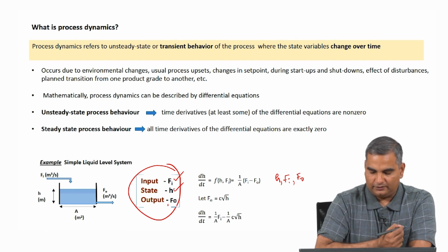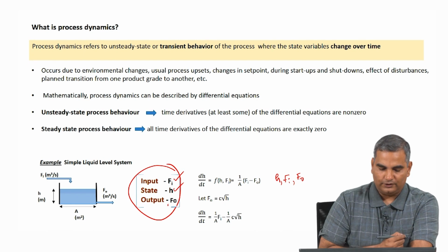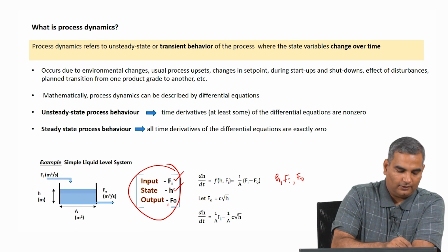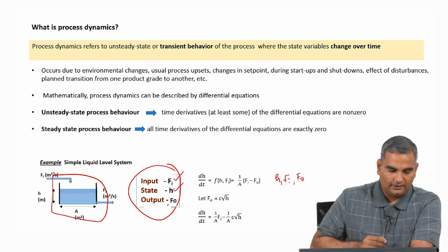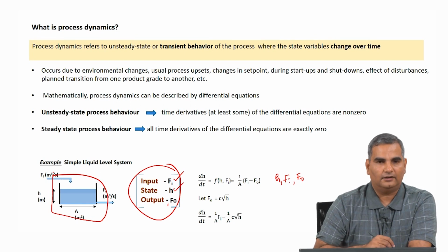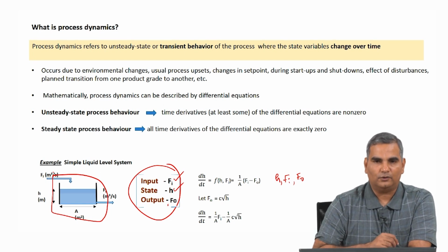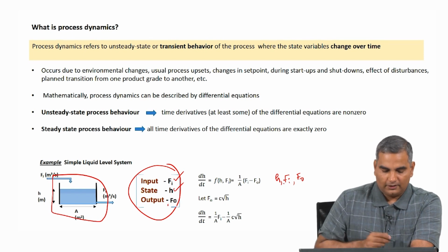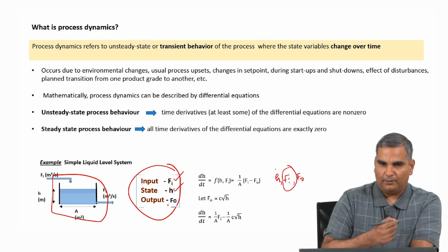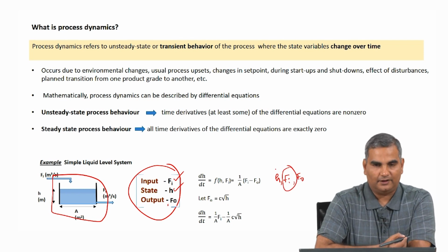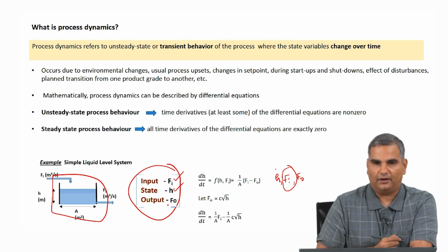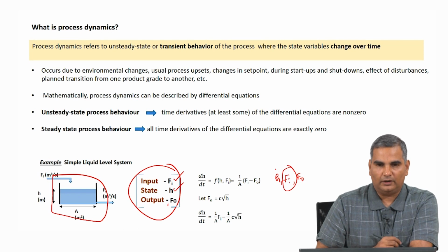And if you think about this a little more carefully, you will notice that since we are writing the equation for the tank, and remember I drew a battery limit something like this, that means that the system equations themselves cannot define Fi. So, Fi has to come from outside. So, what you need to realize is that this Fi comes from outside. So, we do not have to count this as a variable for which we need to write a model equation. So, that leaves us with H and F naught, 2 variables, but I have only one equation.